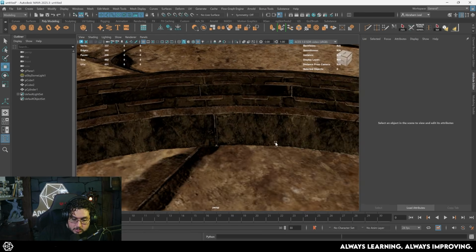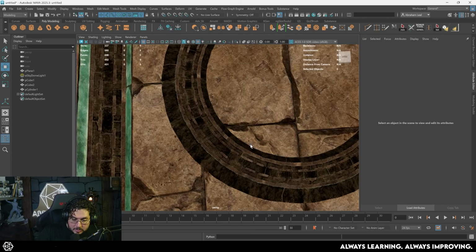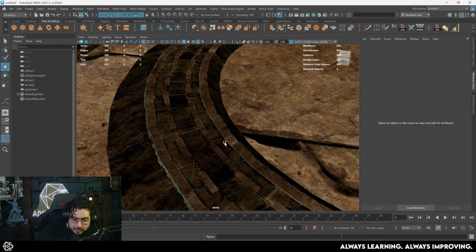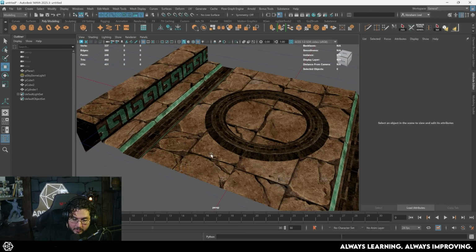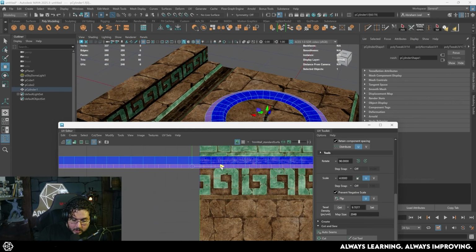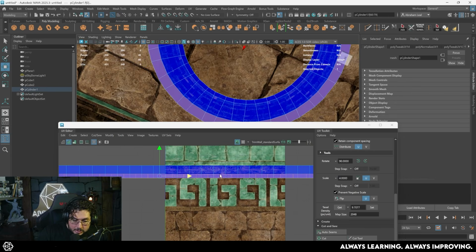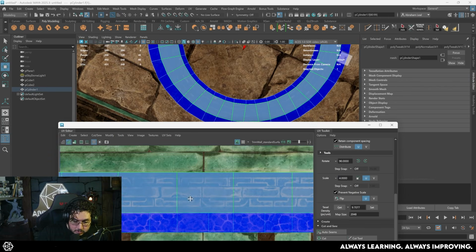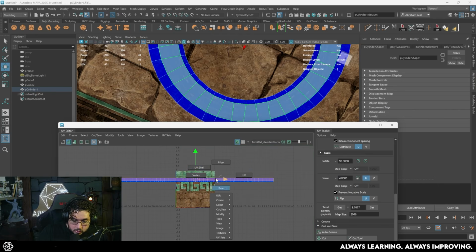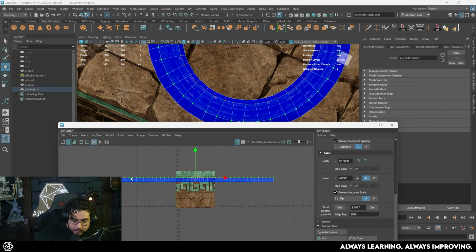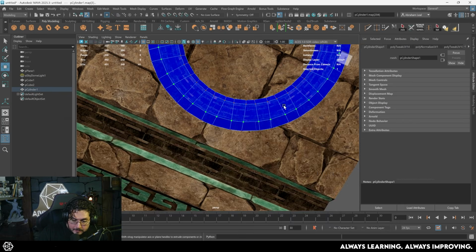I know that right now it looks a little bit ugly because we don't have proper shading with metalness and anything, but it will look very, very nice. The only thing is, let's make sure to correct those little bumps that we have on our element. This one I'm going to move around a little bit so that it's offset from the other one, and the lines are not perfectly aligned. It seems like it's this one that's touching the jade area a little bit. So I'm going to go to my UVs, grab all of the top UVs right here, and push this thing down a little bit more. There we go. Much better.